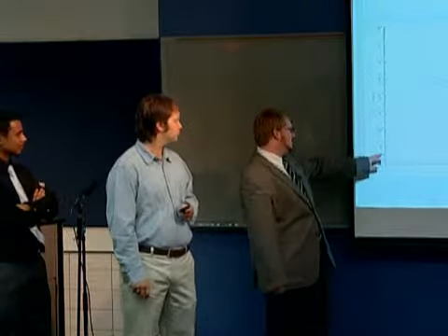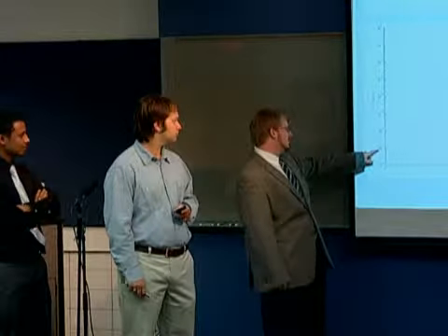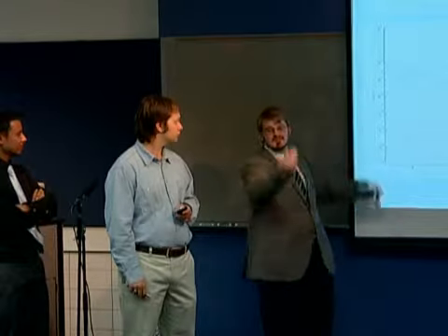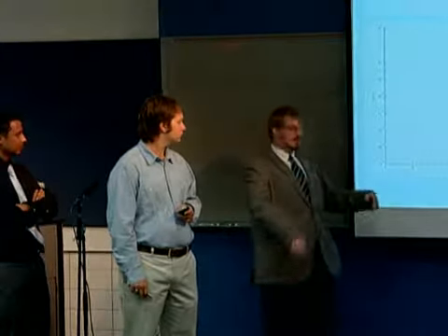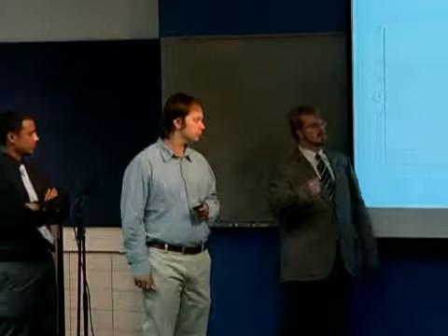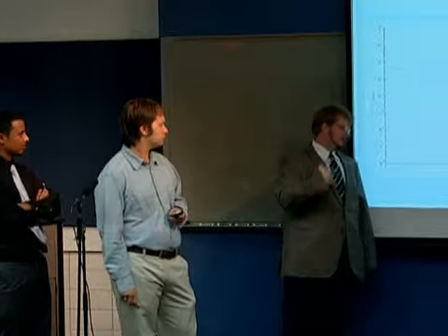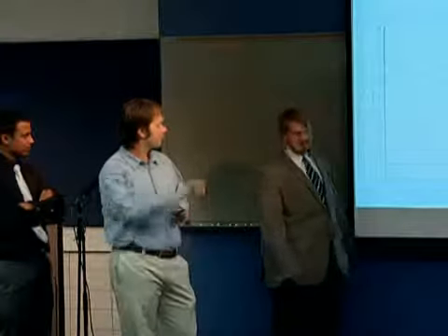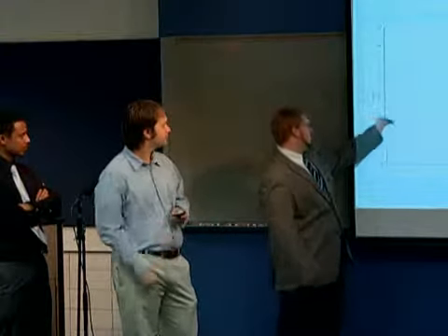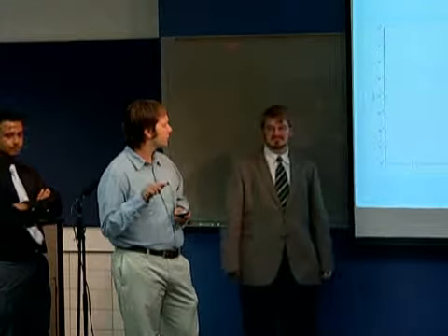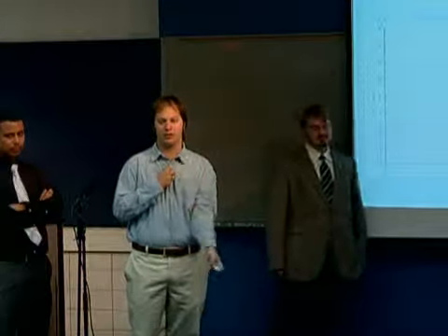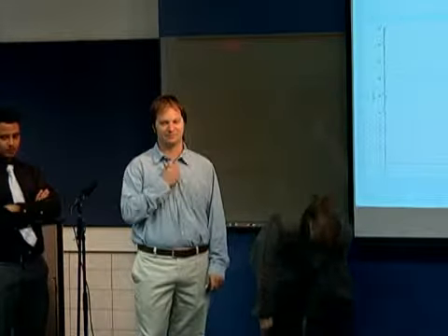That's how you get these really nice numbers. Once you're down here, it's like a million bits per error, and it counts how many errors. It would count up to about 20 errors and do that multiple times. Going down to here might take half an hour. Down here, you're looking at maybe overnight. These curves get smoother as you increase the number of errors. It's just the central limit theorem.